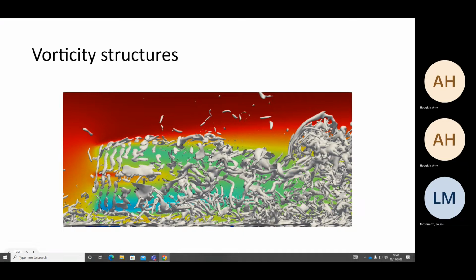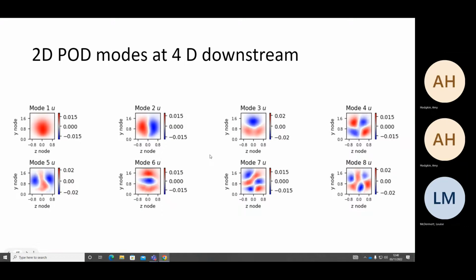So we can see some trace of the helical vortex for sort of three or four rotations, but already it's immediately broken up. And then by the time we get to about 1 radius downstream, we have no visible sight that there was ever a helical vortex there. It breaks up, and the vortical structures of the wake are interacting with the atmospheric boundary layer, and it's much more difficult to see what's going on, basically. So it's much harder to study this in terms of vortex breakdown, but we are trying to think of how we can look at it still and get some clean data out.